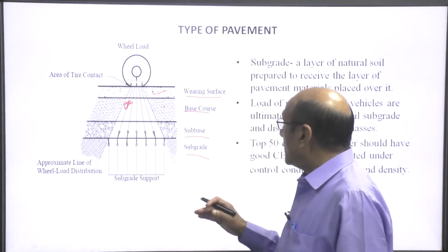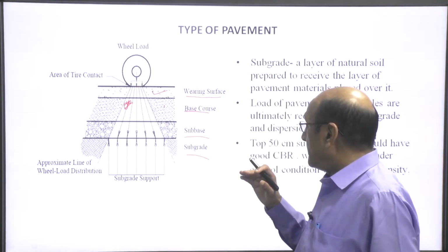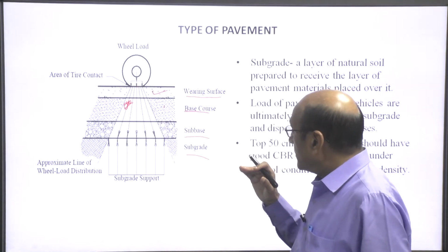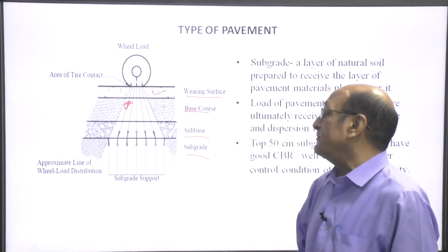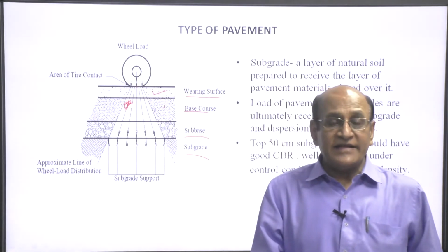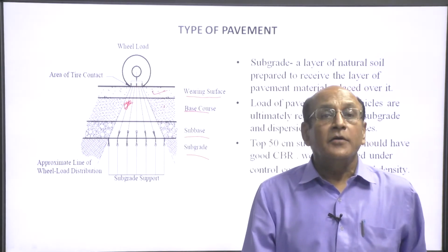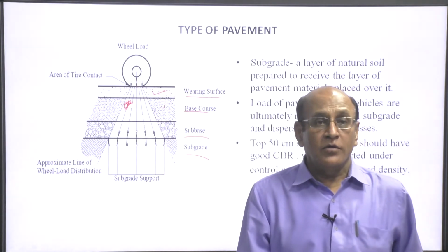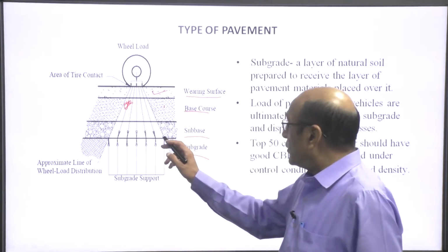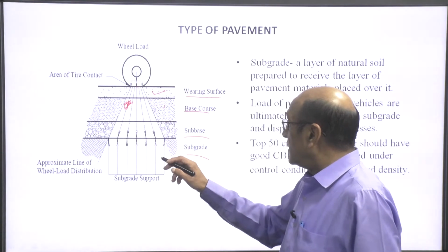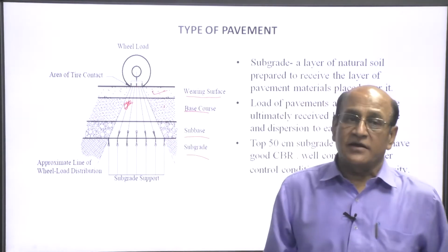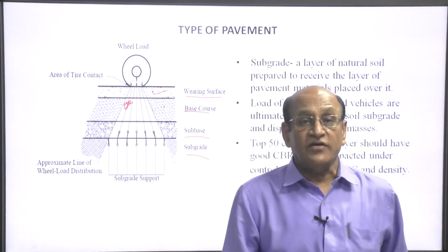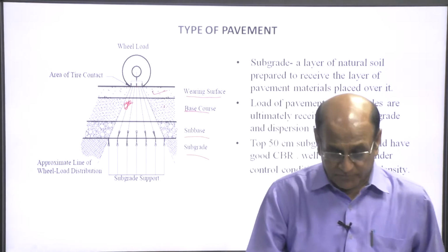Up to the junction of the sub base and subgrade, the stress becomes very low, and it should be less than the bearing capacity of the subgrade. Otherwise, there will be chances of failure of the pavement system.